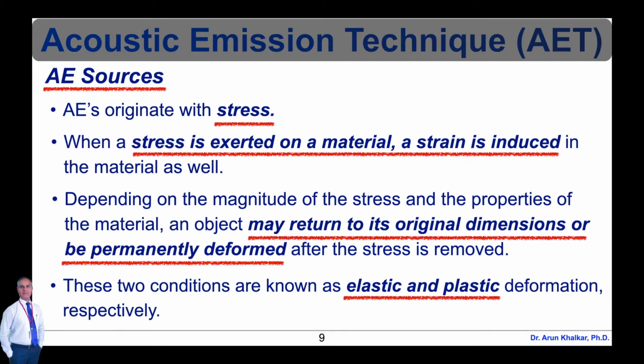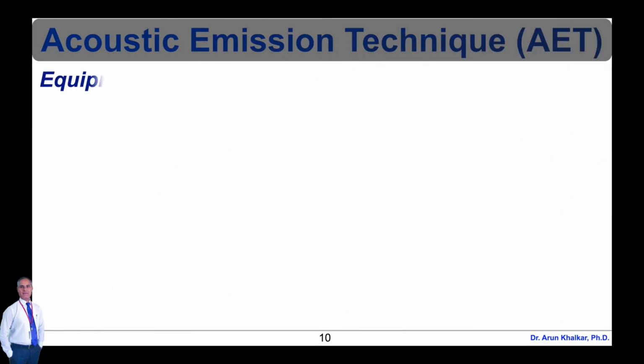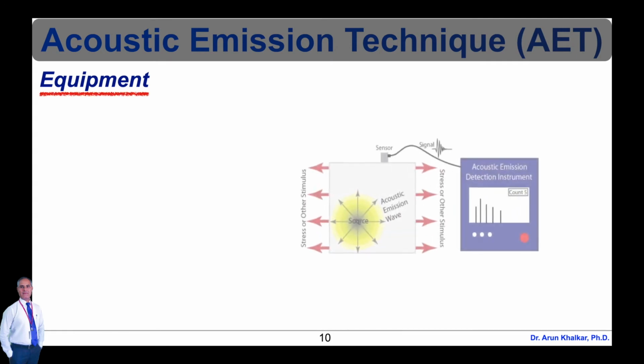When cracks exist in a metal, the stress levels present in front of the crack tip can be several times higher than in the surrounding sound material. Therefore, AE activity will also be observed when the material ahead of the crack tip undergoes plastic deformation, that is, micro-yielding.